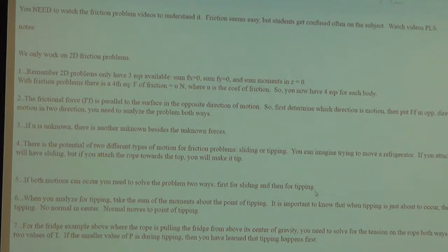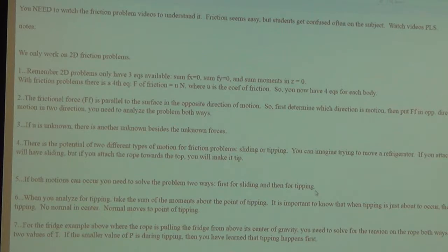So you could think of that 100 pounds as the maximum force for equilibrium. Does everybody get that? Because if you pull it at more than 100 pounds, it's going to slide or tip. But if it's less than 100 pounds, it's still not going to move. So the 100 pounds is the max for static equilibrium. Did everybody get that? Sometimes it's confusing with max and minimum. But when you use static equilibrium equations, it's still static, it's not moving. It's not unless the force is greater than that.